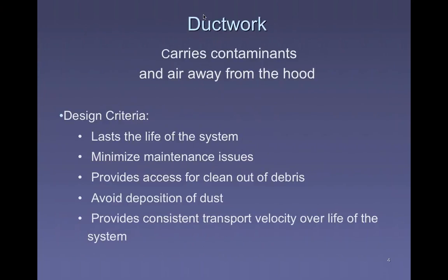If you read through the workbook, they're going to talk about the criteria you should consider when you design ductwork. Among them, and this would seem obvious, is that the ductwork and the system you're building should last the life of the system, because it's presumably protecting workers. Minimize maintenance issues. You don't want debris building up inside of it, so you want to make sure the transfer velocity is good. If you think you might have debris building up, you want to put clean outs there, and so on.